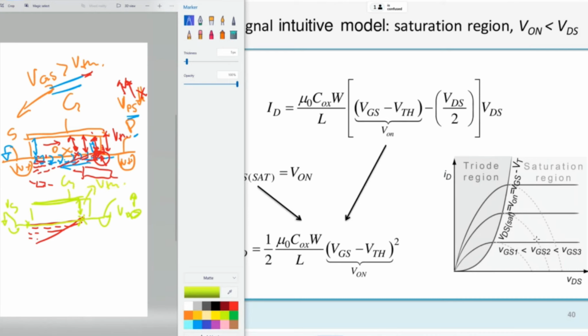Here I'll be much higher than the threshold voltage, and here I'll be less than the threshold voltage. So at this point, I'll have no channel. It will be depletion region. And here is the favorite question that I get from students: how, if I have a depletion region, can the current flow? And it can flow because here I have drift up to this point.